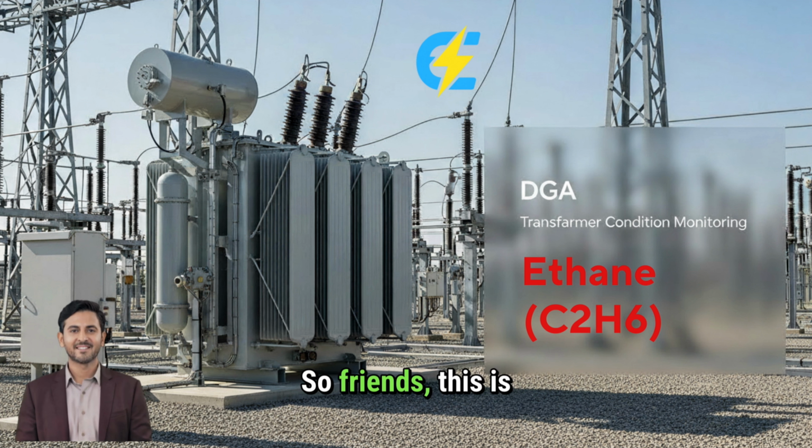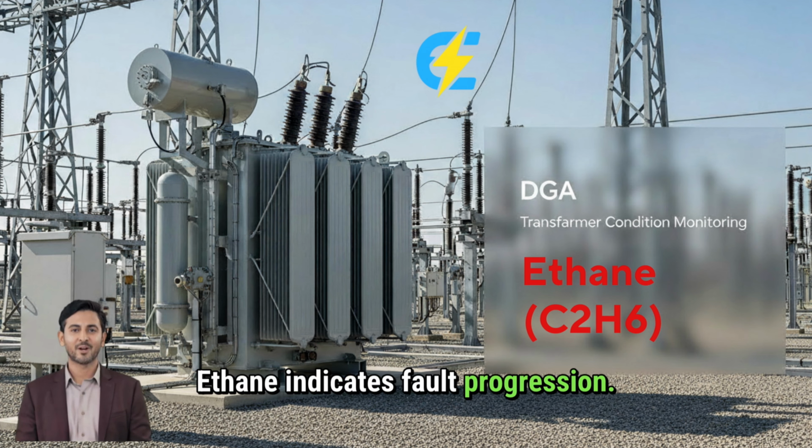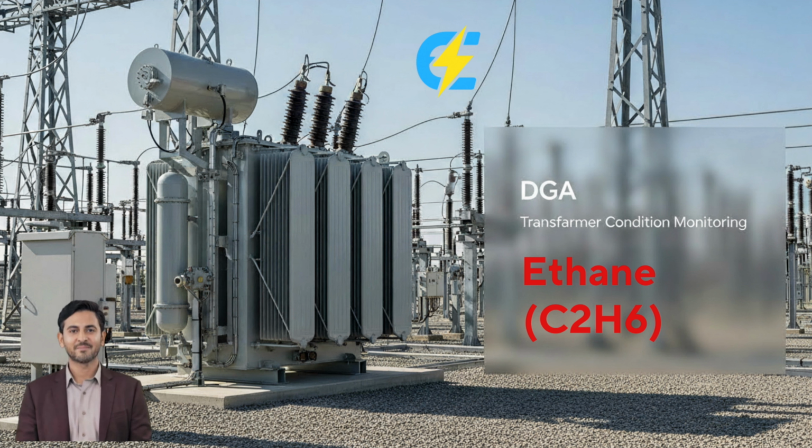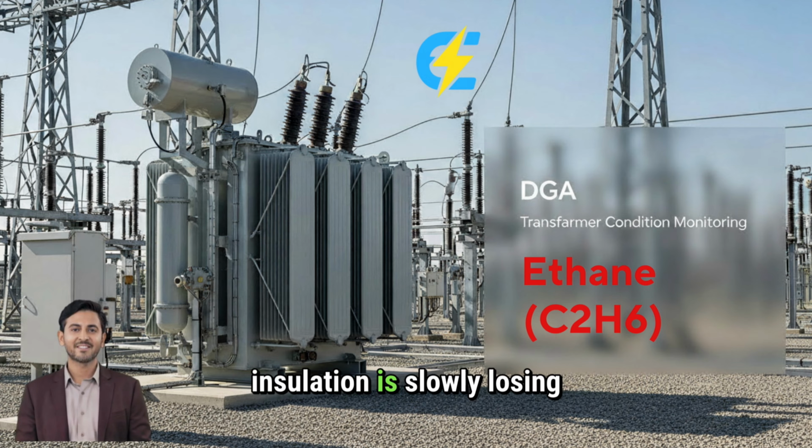So friends, this is the real meaning of ethane, C₂H₆ in DGA. Ethane does not indicate an instant failure. Ethane indicates fault progression. It tells you oil stress is increasing, thermal energy is building up, and insulation is slowly losing margin. Remember this simple ladder.